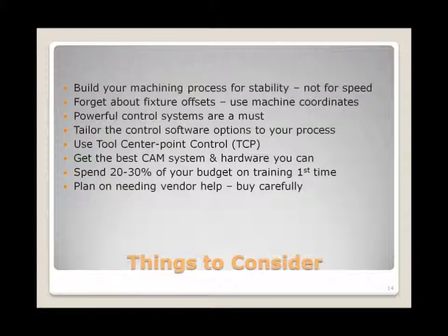You need a very good control system. There are a lot of products out there, lower cost products, where yes, they're a 5-axis, but when you really put them into 5-axis machining, the control system doesn't have enough horsepower to do some of the machining processes that we need to deploy. You want to tailor your control software options to your process.